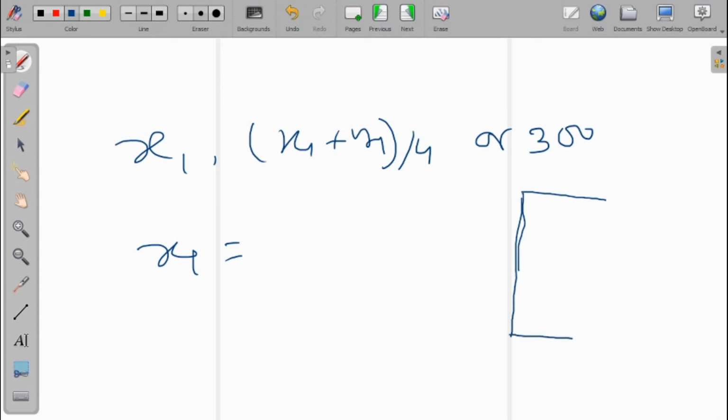So our beam is this. Here we are providing the main reinforcement, then we are providing the transverse reinforcement like that. If you go back to your slides, you will know what x1 is. x1 is basically the center to center distance of the transverse reinforcement. From the transverse reinforcement, what is the center to center distance? That is basically called x1. So how to calculate that?